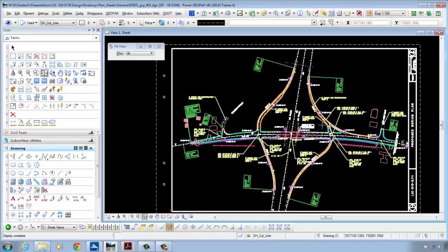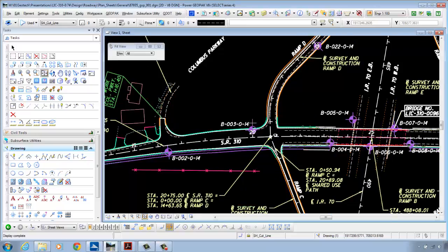That'll make it easier to use the Place Boring Graphics VBA. And then if you have cases like boring number 3 that I want to show on my main line and on ramp D both, then all I have to do is go over in the model and edit the location information in the model for that boring for on ramp D.